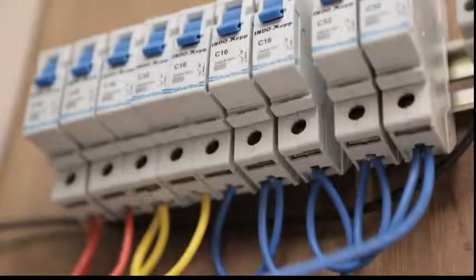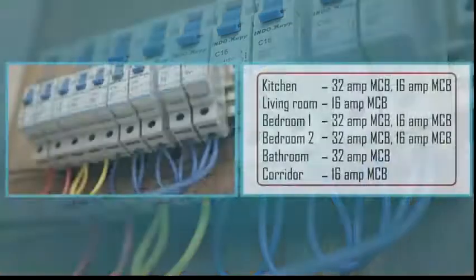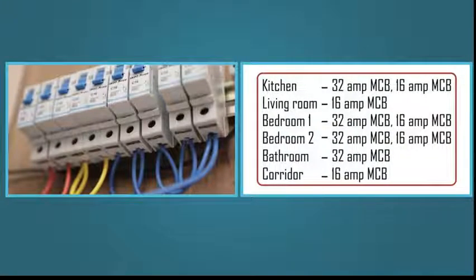For that, take a cut piece of red wire. Insert one end to the input of R phase 16 amp switch and other end to the input of 32 amp R phase MCB switch. The same is to be repeated for Y and B phase bus bars, one 16 amp and one 32 amp switch for Y phase and three 16 amp and two 32 amp switches for B phase. So what you see here is the MCB switch distribution for the various rooms as per the table.